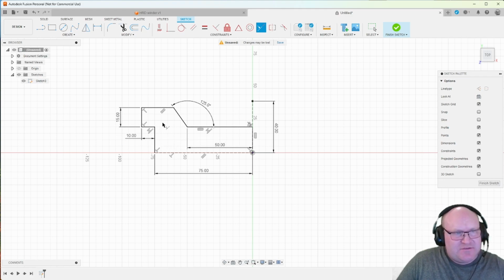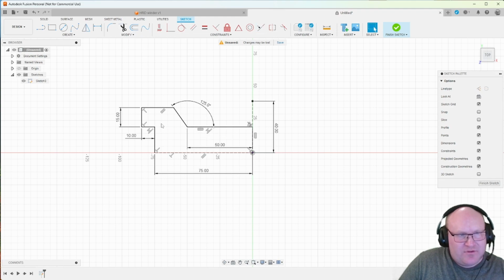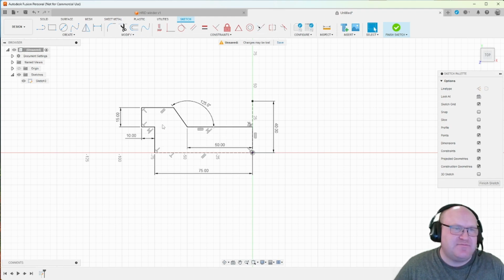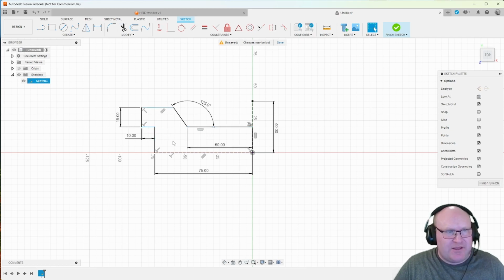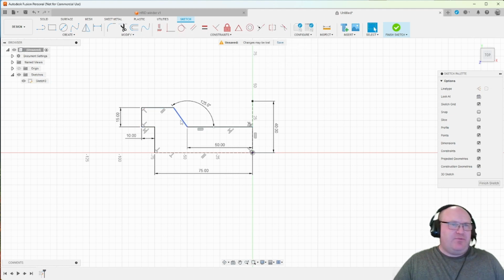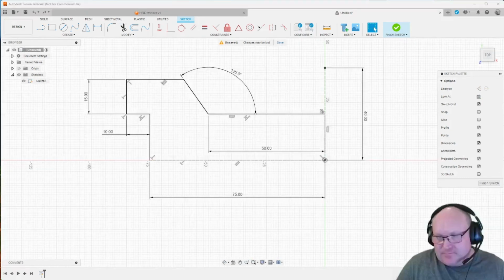And then to exit this mode, you just click escape. Then you won't try to affect any other lines. If you would like to delete any of these sketch relations, simply click it and press the delete key on your keyboard, and they will disappear again. Another way to apply the constraints you have on top here is to pre-select the elements you want to apply them to. Click the first line, hold down Control and click the second one, just as you would with a file in the File Explorer, and then click collinear up here. And that will apply the collinear constraint between them.